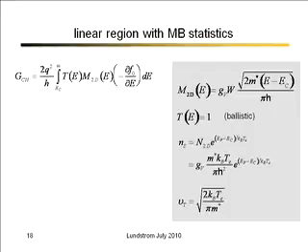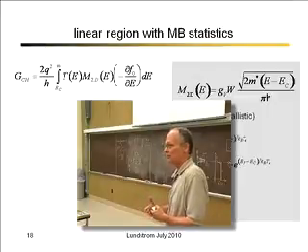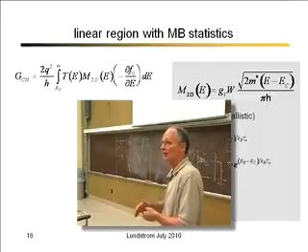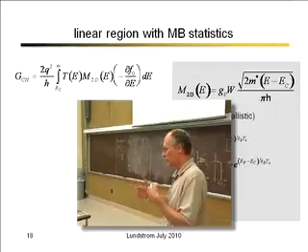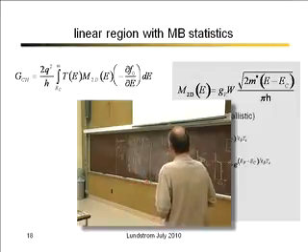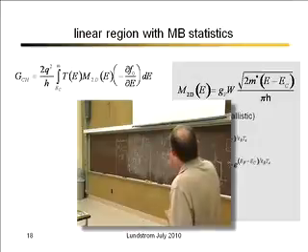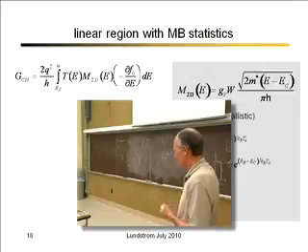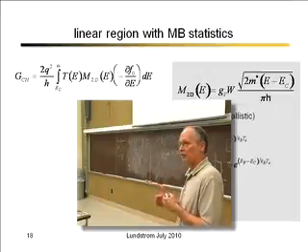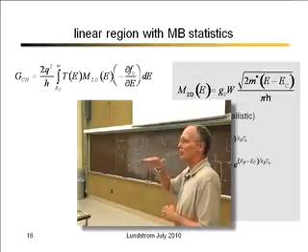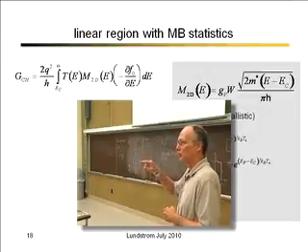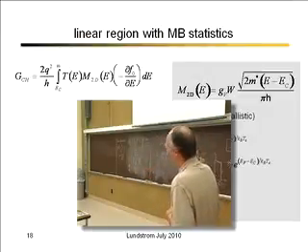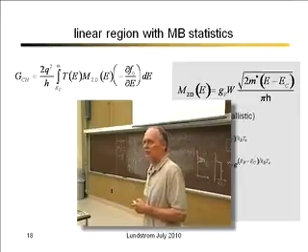But I'm going to do it in a different limit than Professor Dada discussed, the T=0 limit, where he talked about how in general you'll have to compute this average over this broadened distribution minus dF0/dE. I'm going to take the Maxwell-Boltzmann limit. This takes the Fermi function and assumes that all of the states are way above the Fermi level, so the Fermi function reduces to an exponential. Now, that isn't necessarily a good approximation for MOSFETs.